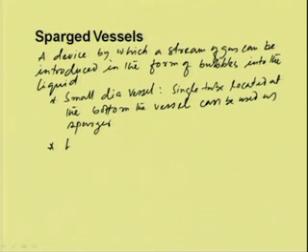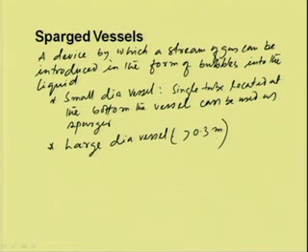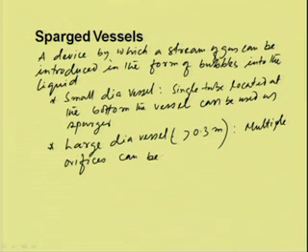For large diameter vessels, say large diameter means greater than 0.3 meter, multiple orifices can be used as sparger.